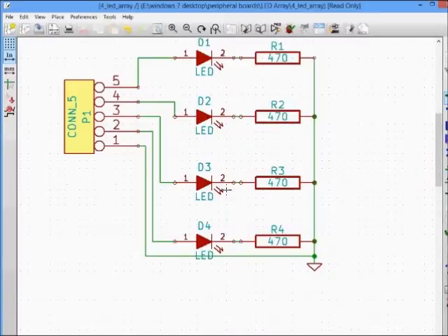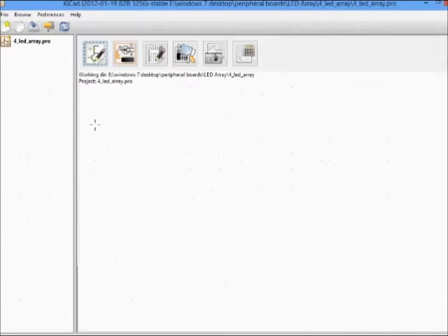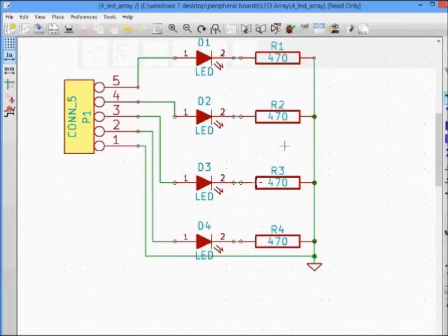Now in this particular step, or the schematic drawing, we have not assigned any footprint to the schematic. So this is the second step, or the second tool that we discussed. This is CVPCB. This is what we use to assign the components the respective footprints. But before we go ahead and do that, this is the important step of creating a netlist. It is basically a list of interconnections, or the nets, which tell the connections between various components in the schematic. So we'll have a detailed look when we go ahead and route the board, but let's just create it.